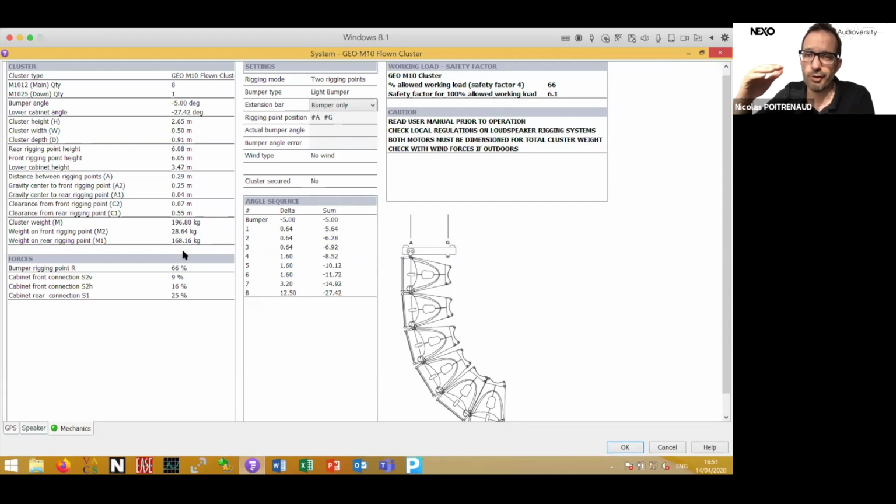Okay, so this is a kind of headroom of safety. It can be 4 times heavier and the system will not break. So this is the headroom. Depending on the territories, depending on the countries, some have very strict regulation, for example in Germany, and they will ask that the system has a safety factor of 4. Some others are 2, but in Germany, for example, it is 4.